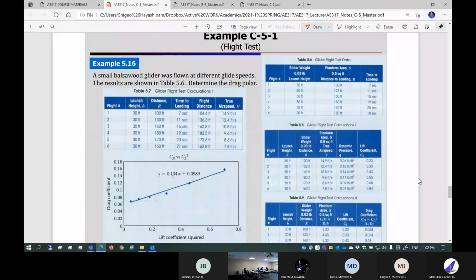So this is a very simple example for Ps determination and also direct polar determination for glide testing. This can be fairly easily done. You have to, of course, coordinate lots of things, but this is something you would probably want to think about in the fall semester as the team members come back. And then if you do this process and compare against X55, this is probably good enough material for professional publication. Okay. All right. Any question?